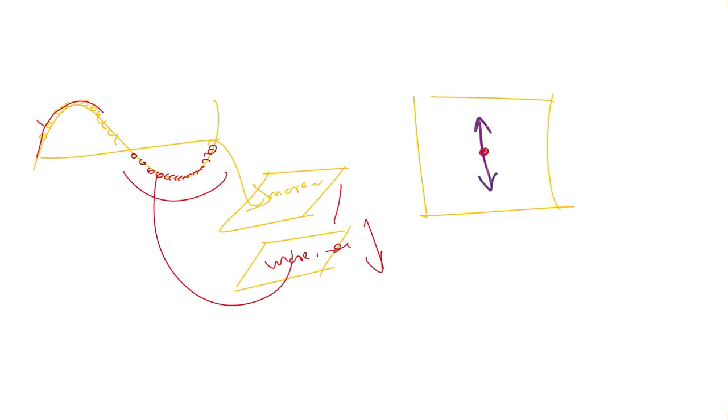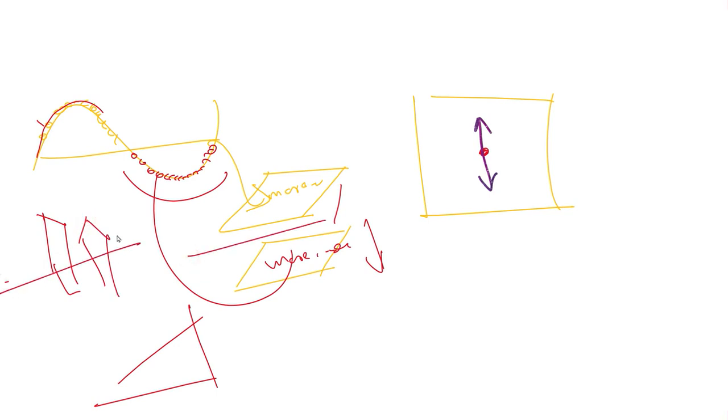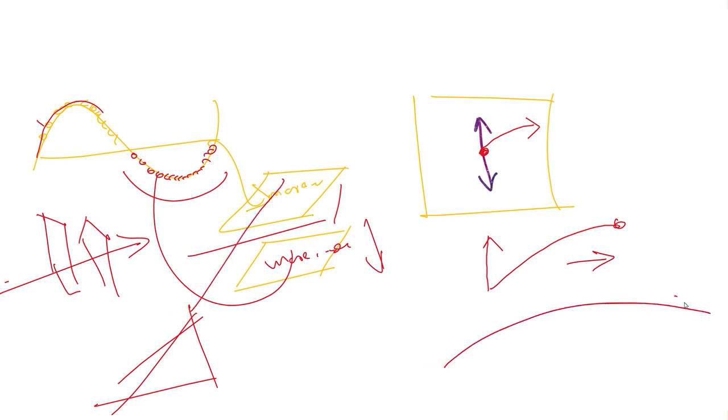Now what we do, we provide a ramp voltage to the vertical plate. So we are having two vertical plates, and we pass the same electron beam through these vertical plates. So the vertical plate with this ramp will move this graph on this side. So it was initially moving like this, and now it will move like this because it is pushed on this side. So the more the ramp, the more it will go on this side.